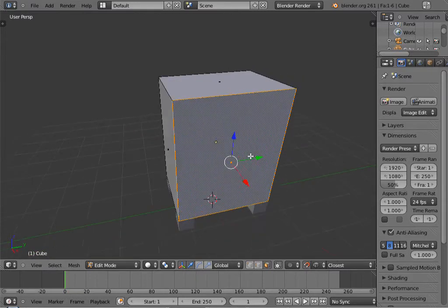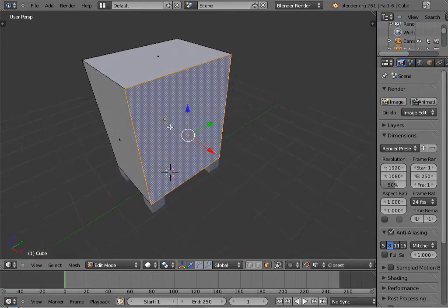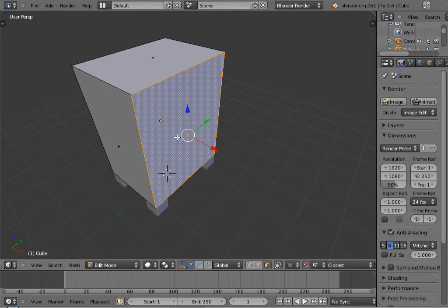So now we've got this face selected. You could do something here with subdivisions, which means dividing up this polygon into smaller polygons. But what I'm going to do is a bit of a weird introduction to extrusions, if this is your first 3D thing. I'm going to make an extrusion of 0 length.